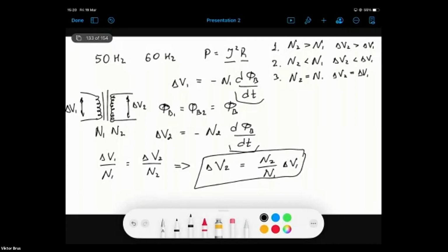So this sounds a bit strange, because why then do we need to use this transformer if it technically does nothing besides losing some energy, because efficiency of these transformers is from 90 to 99%, depends on construction and also frequency. That's another big important parameter. The higher the frequency, the smaller and more efficient the transformers. But this we will not discuss in detail here.